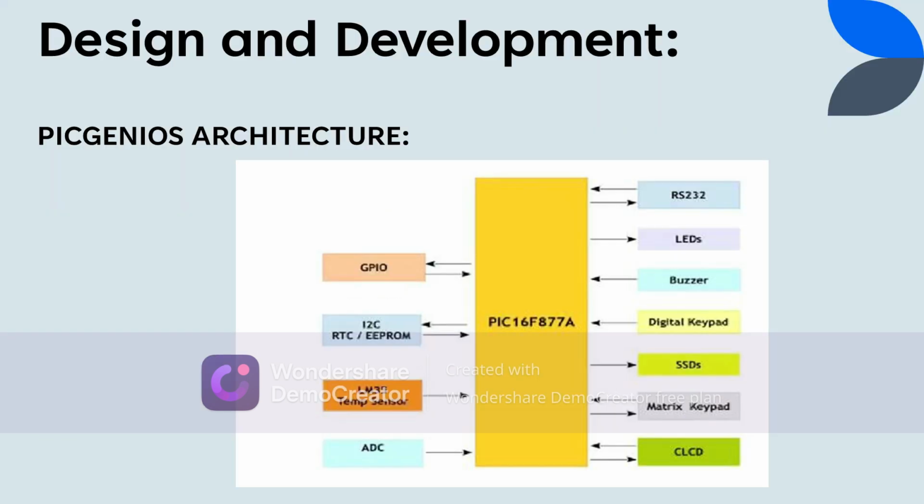And now we'll move to our design and development. So it is our PIC16F877A microcontroller architecture, in which we have various inputs and outputs. Some of the components act as both input and output, like GPIO, I2C, matrix keypad, CLCD, RS232, etc.